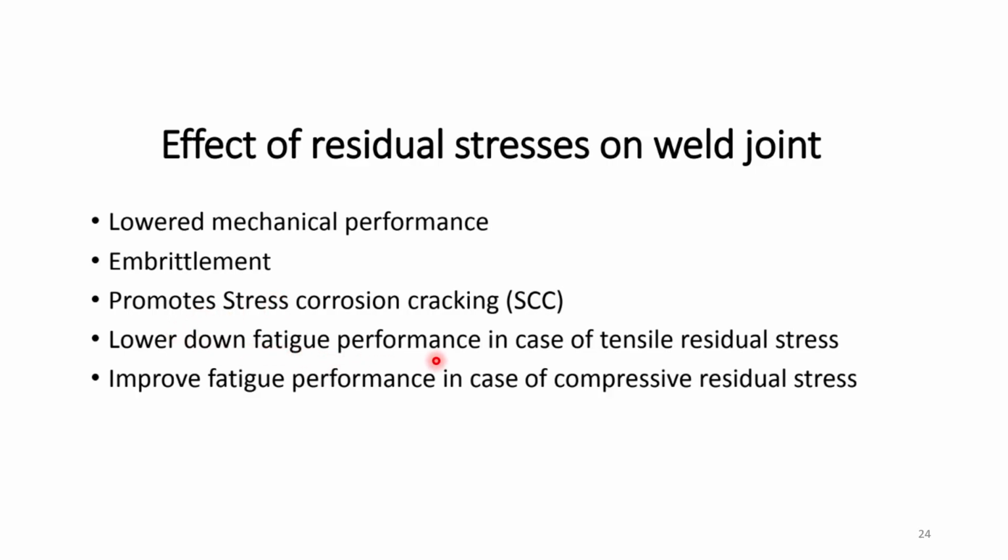Lower fatigue performance in case of tensile residual stresses. You must already know that if there are tensile residual stresses, it always lowers the fatigue performance, while compressive residual stresses improve the fatigue performance. Because when we consider fatigue loading, we mainly go for loading which is of tensile type or at the neutral line.